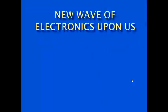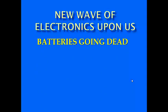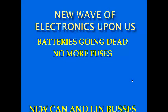There's a new wave of electronics upon us, however. Batteries going dead doesn't mean that we've got a bad cell in the battery anymore. It could be a variety of reasons why. The charging system is operating normally. It's the parasitic draw problem that we're starting to see now with power mode situations on most manufacturers. No more fuses. Open up the hood on a typical vehicle today and you might see 4 fuses. Now we're seeing TIPMs and smart junction boxes replace fuses. How do you test those? What happens when those blow? How do we reset them? There's no fuse to put back in.